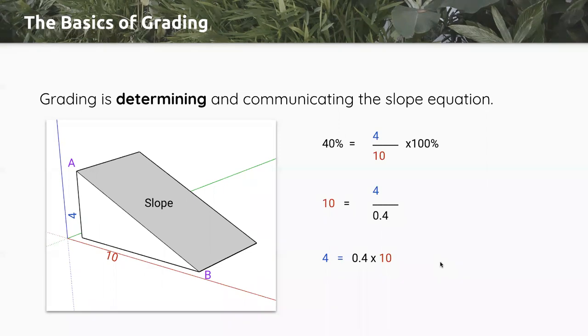Things that I can recommend to start practicing and really getting into memorizing this equation would be to make 2 points on a piece of paper, just that simple, and pick a scale with a scale ruler, any scale. That's really good practice to flip between scales. Then measure the distance between the 2 points and pick either a slope or a height, and then figure out the other one that's missing.